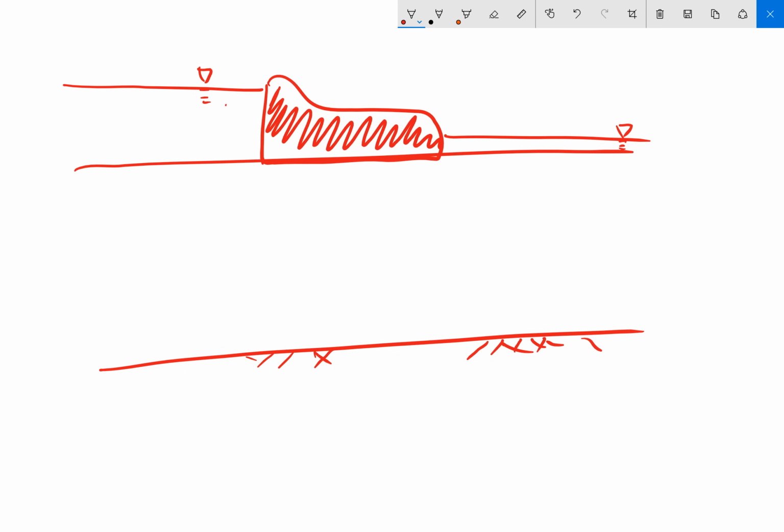We also have to respect the boundary condition, for instance, that any point here on this initial ground surface has the same total head. What do I mean by that? Well, imagine again if I put a piezometer down to that point right on the ground surface. How high is the water going to rise up in that piezometer if I just leave it alone? Well, it'll rise up to the top of the water surface.